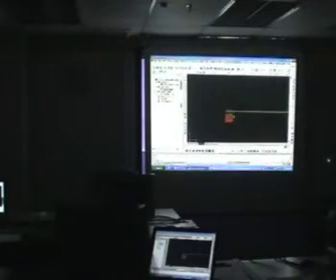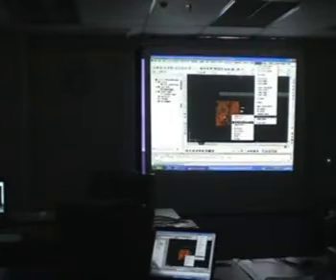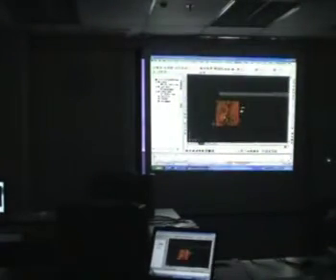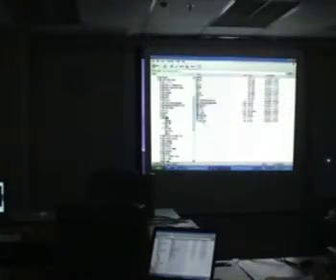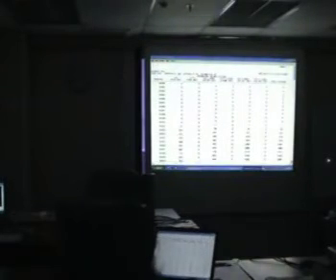Now, if you need the volume calculations by section, you can also generate it here under volume report. Okay, let's say I use the Parcel Method. I'm just going to hit OK. And again, now it's generating the text file. Calculations are done. It's placed in here under the file name output.prn. I'm just going to rename this to sections, and we're going to open that up so you can have a look at the section report.